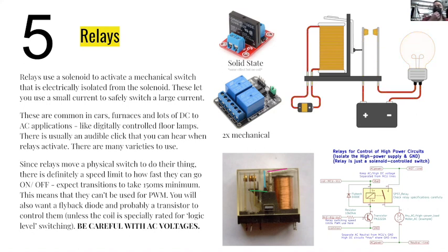Good question. So for PWM, like on a relay, PWM has to switch very, very quickly. If your device can't switch quickly enough, you can't do PWM with it. Relays are the example of that. They just don't have it mechanically, they can't go fast enough.